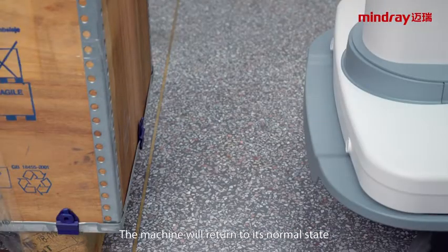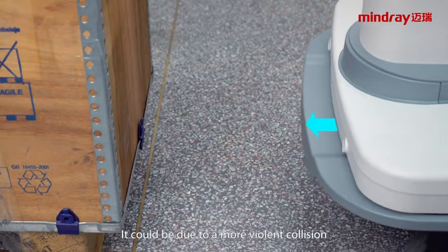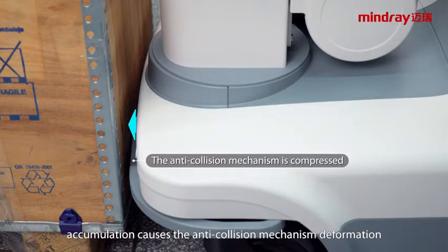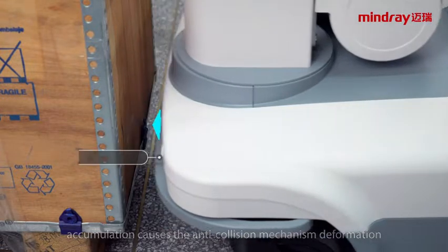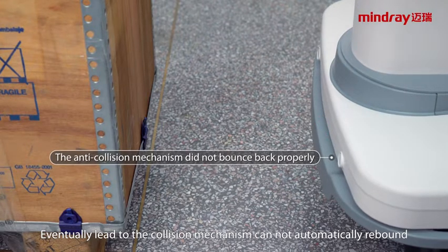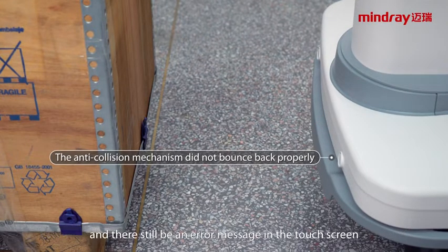The machine will return to its normal state. But in some cases, due to a more violent collision, or many collisions accumulating, the anti-collision mechanism may deform, eventually leading to it being unable to rebound automatically, and there will still be an error message on the touchscreen.